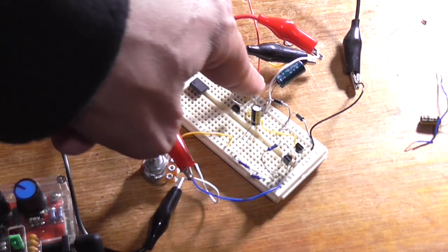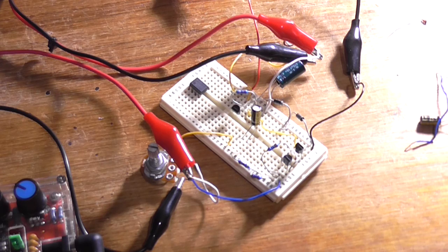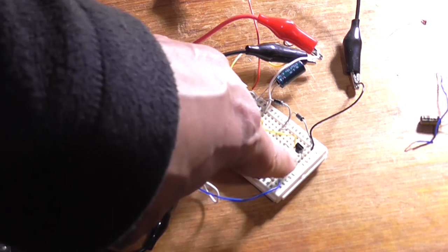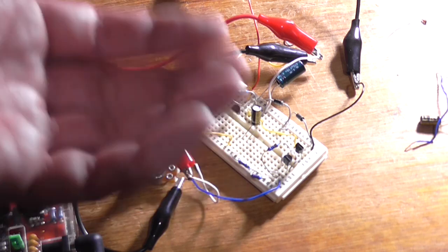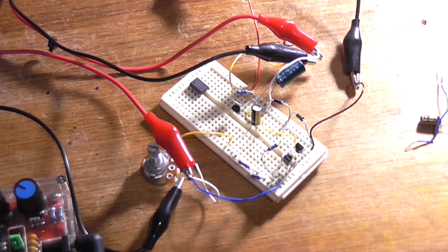Now I'm using two 1N4004 diodes there because I don't have two 1N4148s or 918s. So I have to use those two. It should still work, I don't see any reason why not. And I was pre-testing before filming. Make sure you get these two BC327 and 337 round the correct way, or the magic smoke will escape. Pity I didn't catch that on camera.